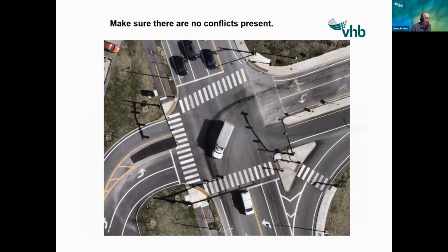We stopped the inspection, called the resident in, and we had the contractor come out and make that change, because the last thing you want to do is leave a conflict at an intersection and have the chance of a sight impaired person getting that go indication from that vibrating arrow, that button, and having them go across the street on a 90-degree conflict with 45-mile-an-hour traffic. So it's real important to check that out.